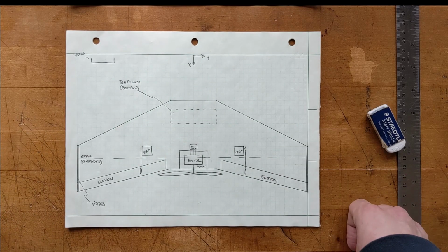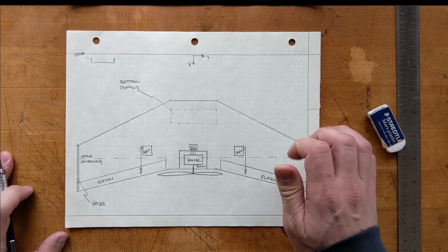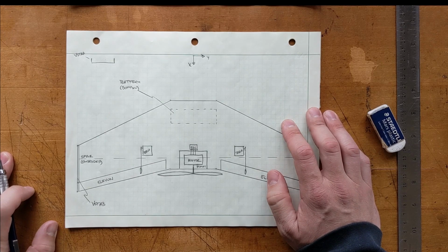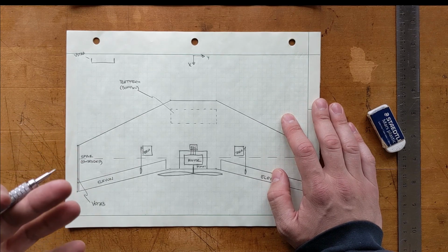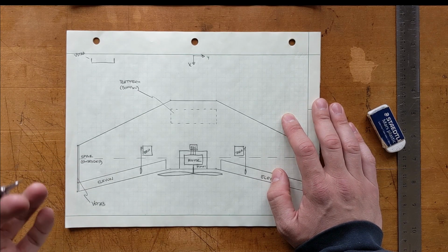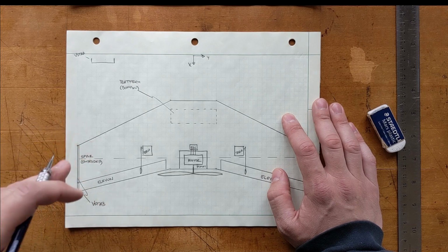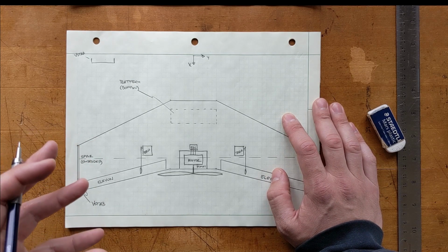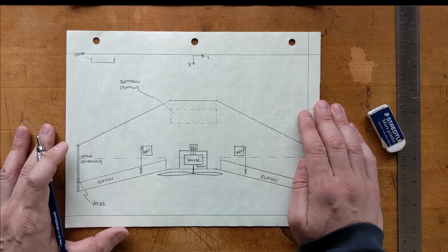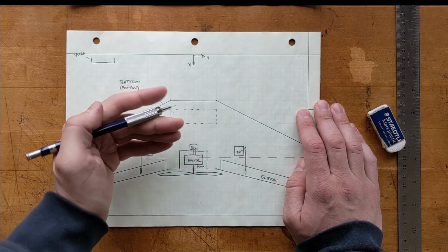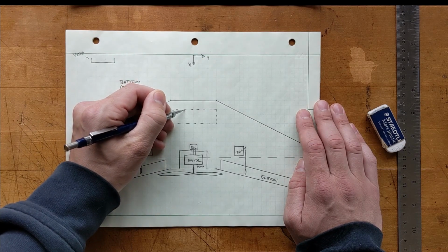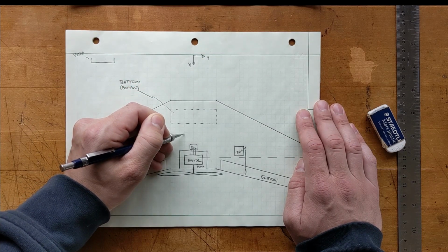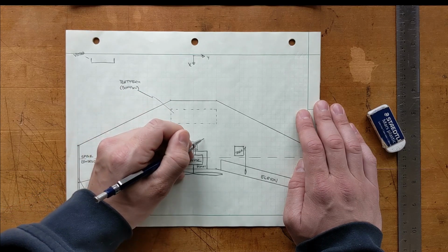Now, from requirement 8, we're going to need flight modes and autonomy. And to do that, we're going to need a flight controller. That's going to be the brains of this aircraft. It's going to do an awful lot for us. Because it has stabilization, it uses inertial sensing, so it measures acceleration and rotation rates. And because of that, we want it located as close to the CG of the aircraft as possible. And that CG is going to be biased towards the front, as I said before. So let's say we'll put it on the center line somewhere, I don't know, somewhere like this.